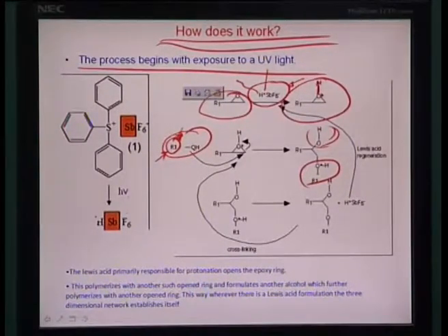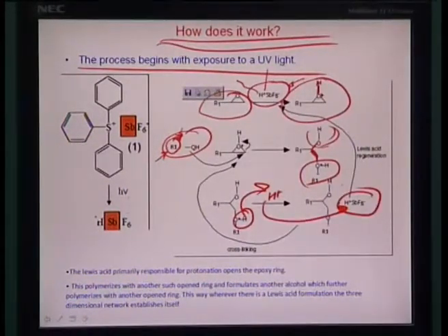Okay. So this is how the Lewis acid giving a proton, H plus, has already opened up the epoxy ring from a triangular orientation into some kind of a double alcohol compound which is formulated here. And in the third step, essentially what happens is that this H plus comes out as a proton and again mixes up with this photoacid generator, S plus H plus SbF6 minus. So, H plus here, or this whole compound here, is nothing but a catalyzer.